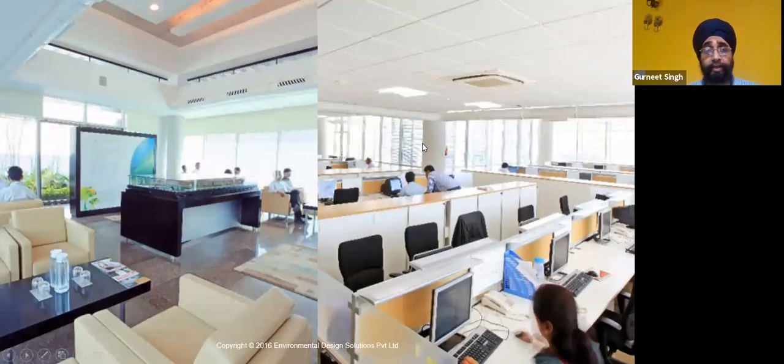The other things that Suzlon has done is they have really gone into efficient interior lighting. The lighting power density was lower than 0.7 watts per square feet. They also coupled the daylighting with the interior lighting through sensors, so they connected it with occupancy and daylight sensors.